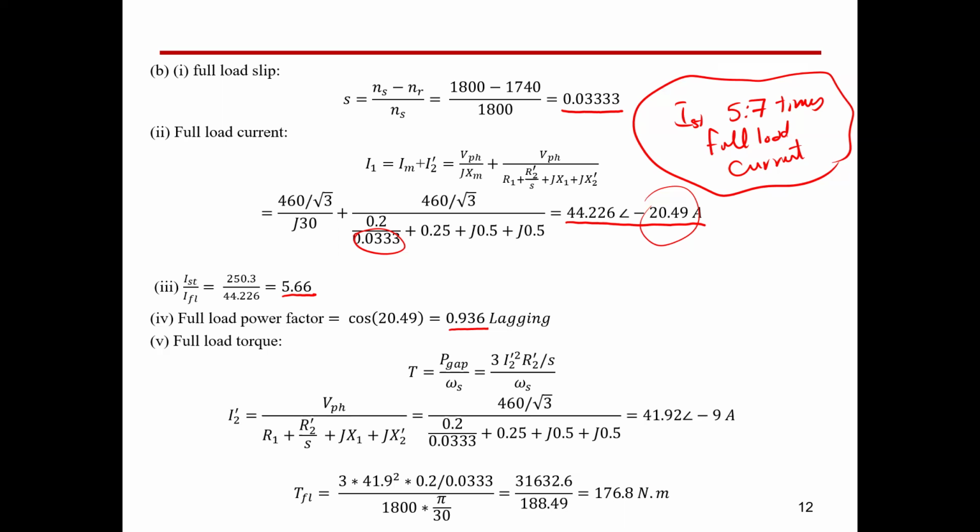So power factor is not important for the transients. It's very important for the full load operation or the operating condition, because the machine will absorb reactive power during operation. But it will absorb very high reactive power in the transient period, though this lasts just a very few milliseconds. For sure, it depends on the machine size.